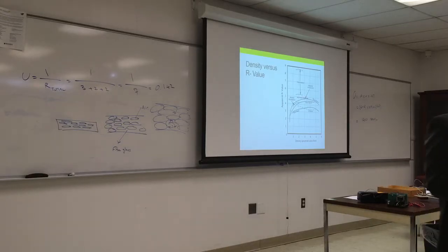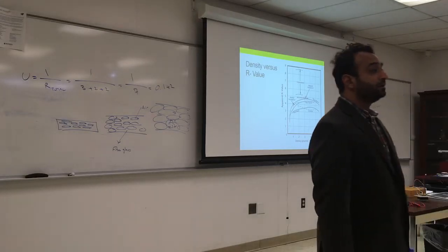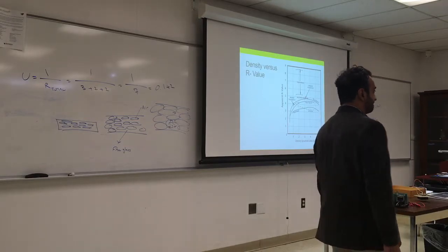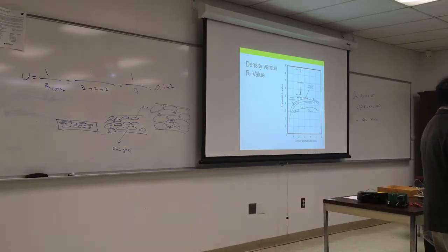These tiles here are asbestos. They're good in place. Unless you cut them and it becomes airborne, there's no problem. Why are asbestos tiles legal, but the asbestos insulation is not? This is an old installation from the 60s. You're not allowed to install this again, but if you have it, you keep it for now.